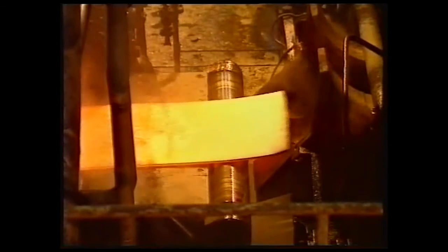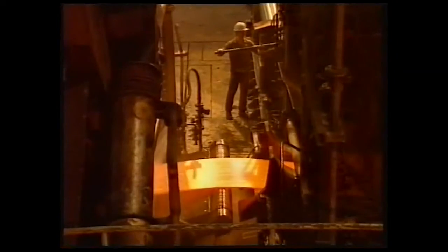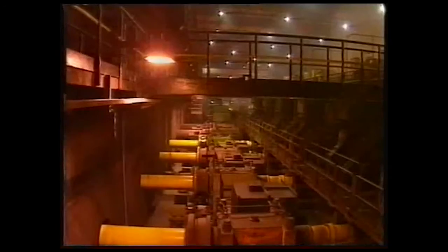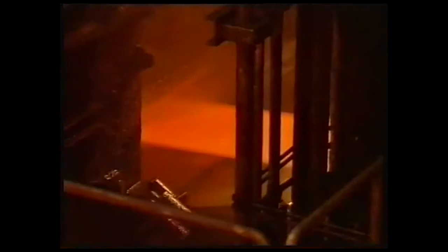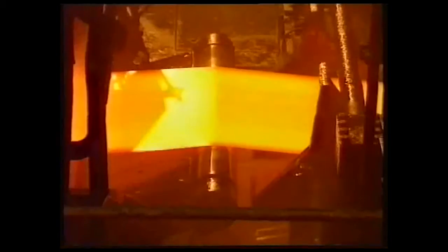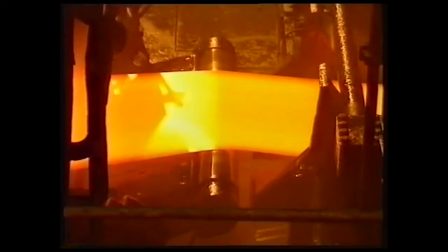The crop is positioned after the vision system and just before the finishing mill. In the 6-stand finishing mill, the bar speed increases from stand to stand because of the decrease in plate thickness. Perfect synchronization has to be achieved in such a way as to keep the material flow constant between the different stands. The slightest tension on the material gives rise to a width constriction. After coiling, not shown here, the coils are transferred to the cold rolling mill.